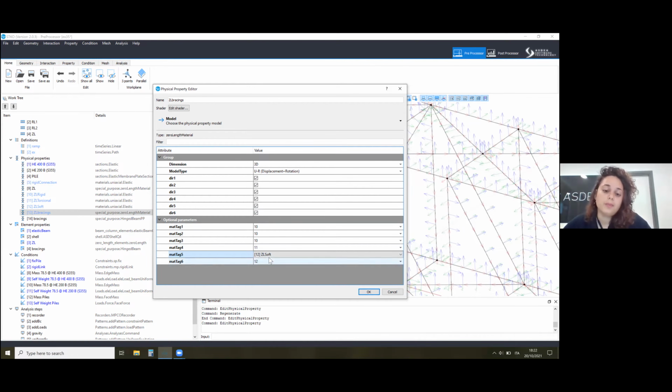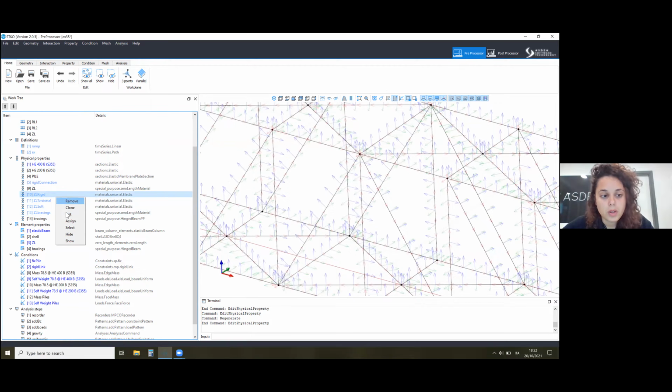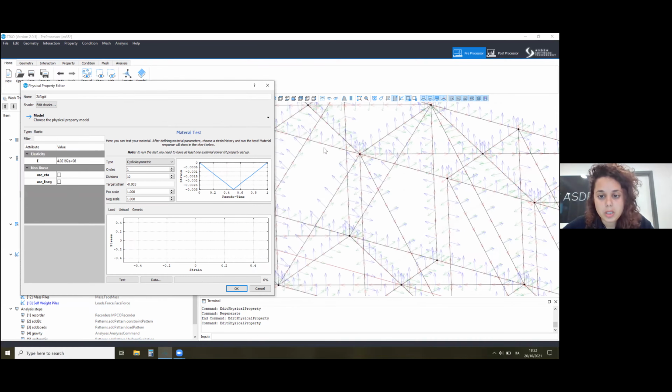If I know the stiffness of the joint, I can use a specific stiffness to give a softer stiffness compared to the rigid one, in this case, for the rotational degrees of freedom, or I can give none. So it depends on what you know about your structure. And how do I calculate these kinds of stiffnesses? For the rigid one, I want my largest section in the joint to provide as much stiffness as that element can yield. So for the penalty method, I make this kind of calculation in which I say, okay, my E is this number, then my area is this number.